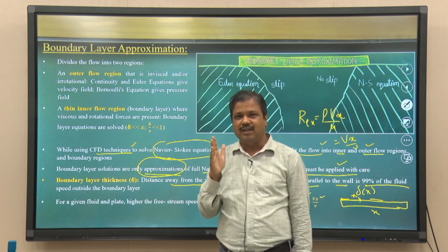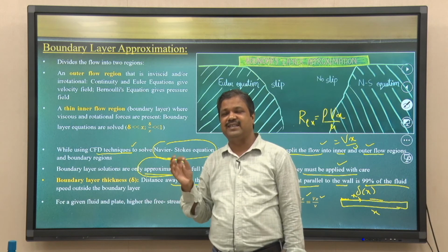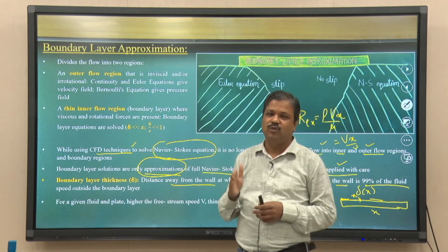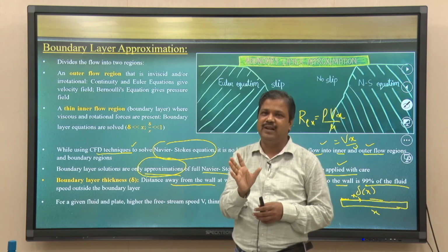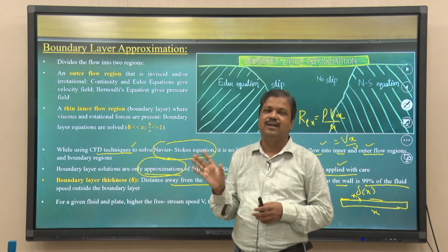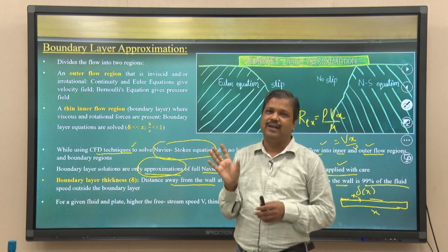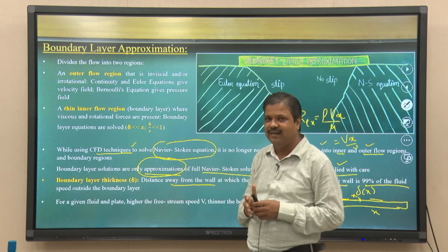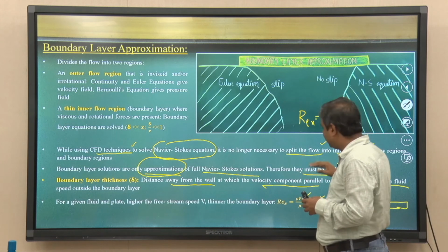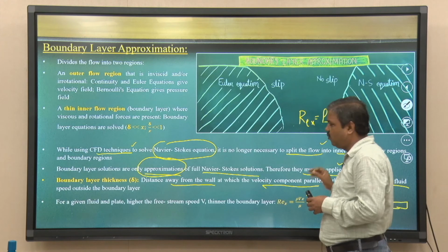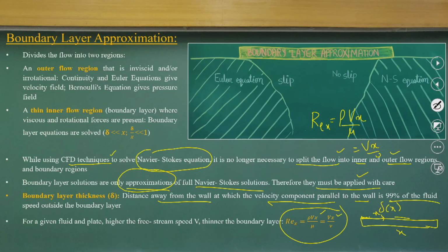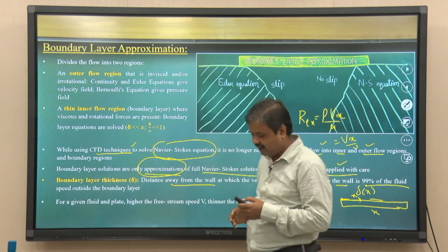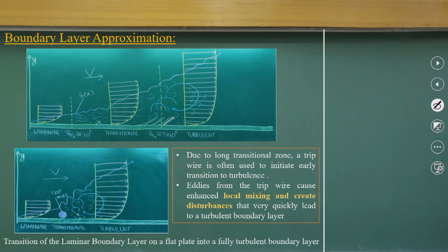Here it depends upon the threshold, the critical Reynolds number, based on boundary layer experiments done almost 100 years back, to find out which region follows laminar boundary layers, which region follows turbulent boundary layers, and which region lies in between as transitional. These critical Reynolds numbers are estimated from experimental data, conducting plate experiments in wind tunnels, estimating velocity observations and the flow field, to define the three regions in the boundary layer itself: laminar, transitional and turbulent.